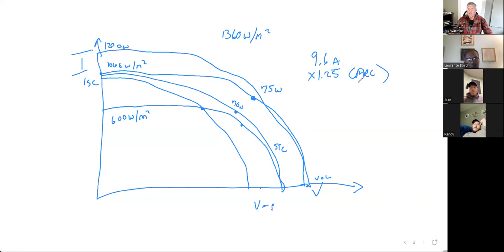Every single circuit you design in solar, in electrical, heating and air conditioning, whatever, you're always going to have that 1.25 safety margin. But in solar, they say before you hit the first piece of electronics, put in another 1.25 variability of solar margin. And that's because we can experience days where you're actually getting more sunlight than what it was rated for at STC.